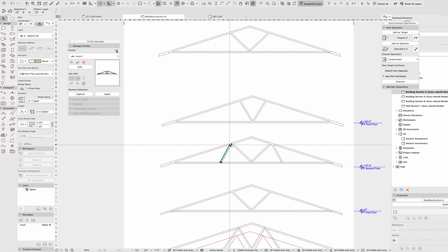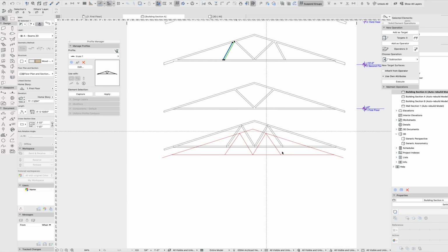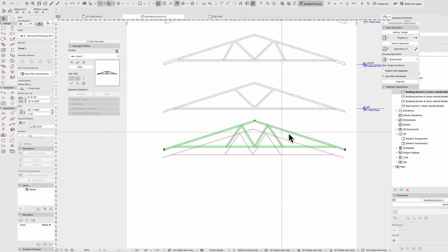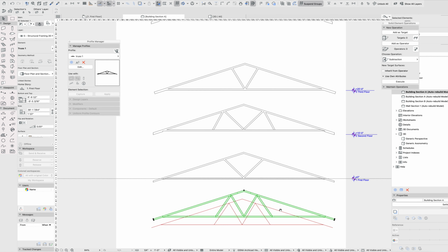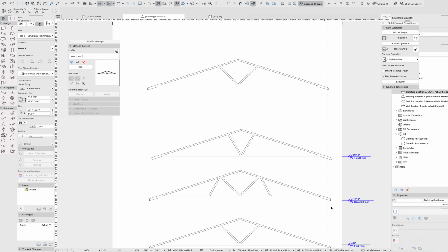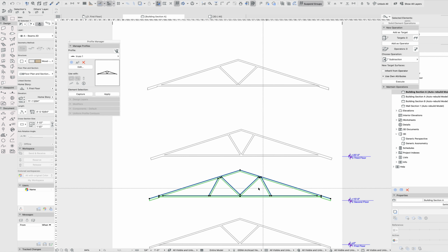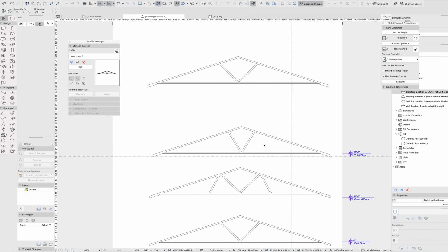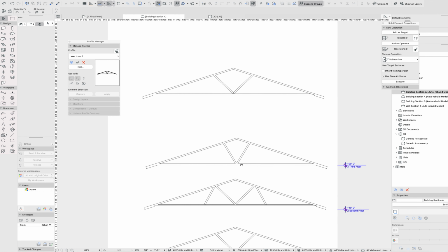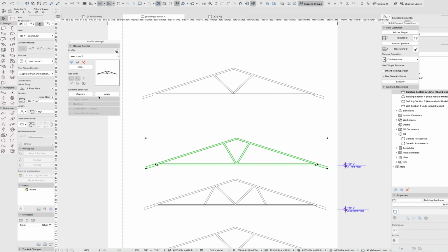And because it's a beam, it's based on that reference line extrusion, not based on the center of chord, which is always really tricky to get the truss maker to work with. And if I need to update the truss in the model, if I decide to save it as an object, you just go back to plan view and save over the top of the other one, just like we did with the truss maker. The fourth option here is also a very popular one, using the beam tool.